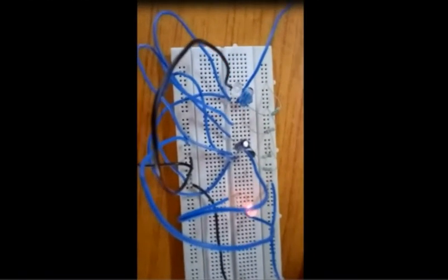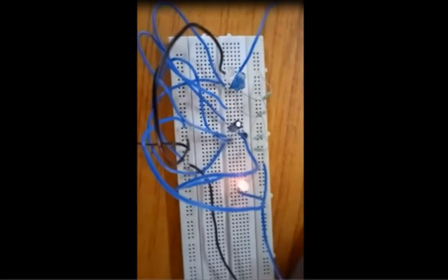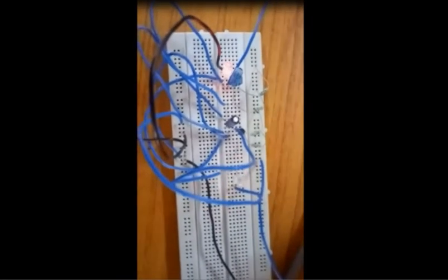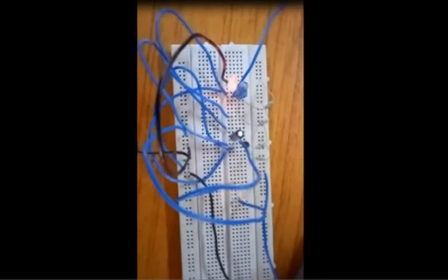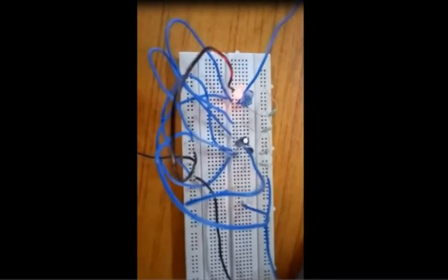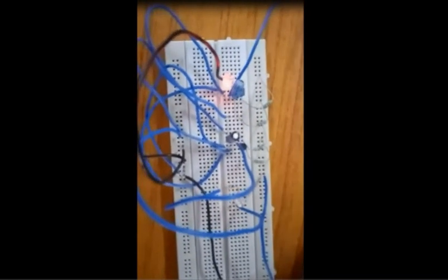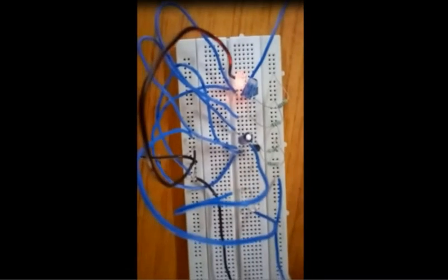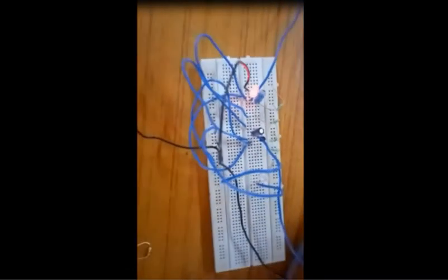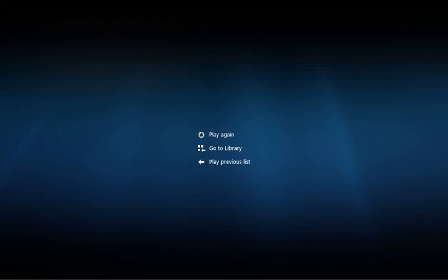We can also design it so that the output can be observed with the help of LEDs. Here, with a small change, the capacitance is replaced by a 10 microfarad capacitor for charging and discharging. Based on that, the LED is blinking.